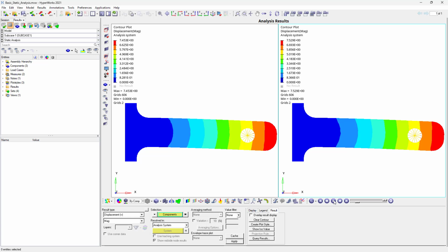In this particular example model, we had seen how we can set up the deck, and with that we tried to run the basic structural analysis using simple boundary conditions, that is RBE3, RBE2, SPCs, and the basic load application.